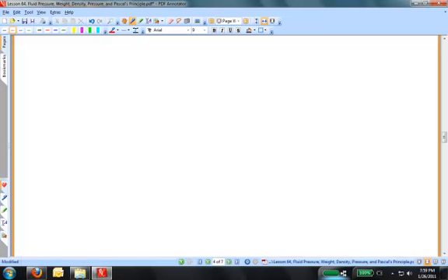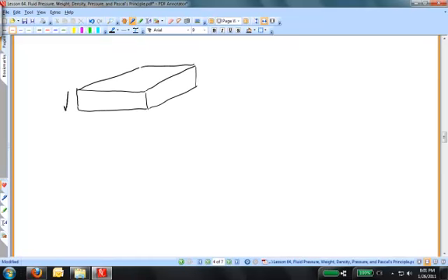And I can choose any shape I want for my liquid. So I'm going to choose a nice rectangular slab. This slab has a height that I'm going to call h, and it has an area on top that I'm going to call A. Of course, the area on the bottom is also going to be A. The pressure here on the top I'll call P1, and the pressure down on the bottom I'll call P2. This liquid has some density that I'm going to call rho. And so this rectangular block is going to have a mass of rho times V, which is rho times the area times the height. That's the mass of the block of fluid.